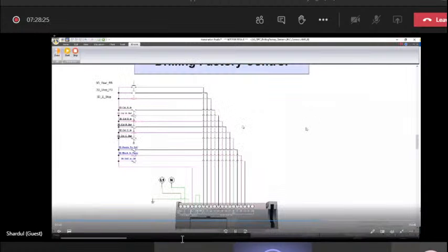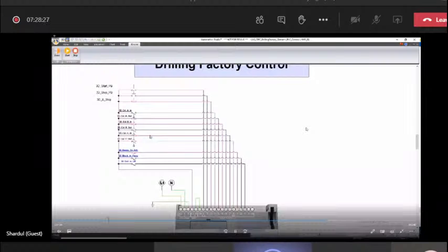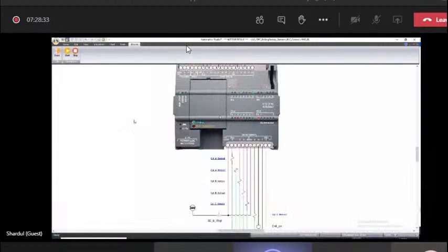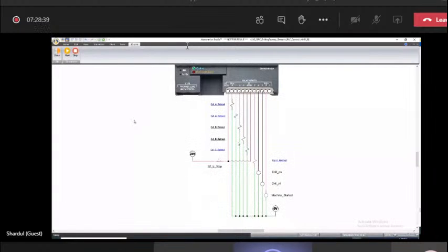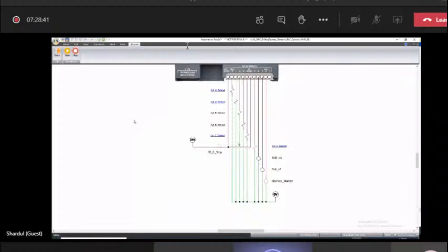The proximity switches, the proximity sensors used on top of the cylinders, are created in Automation Studio. The proximity sensors basically sense the position of the cylinder. They give the supply to the switches, and the switches in return give supply to the input cards of the PLC.